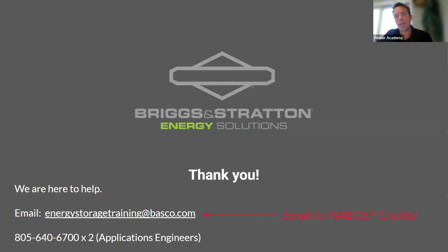So it is important to make sure that the cable lengths are the same, that the systems are as symmetric as possible, to make sure that each of the batteries is doing their appropriate amount of work. So for us, the limitation is purely communications, and it's a product decision. Overall, we decided to limit based on comms to 18 batteries, 6 stacks of 3.